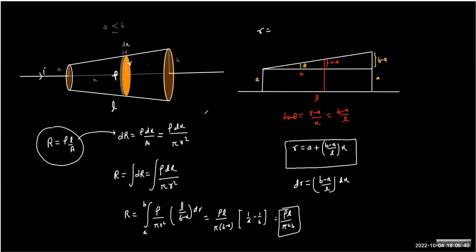And there's a very famous trick for frustum questions. You can just take the thing as a cylinder and replace the radius by the geometric mean of a and b, and then write the formula for the resistor, isn't it?